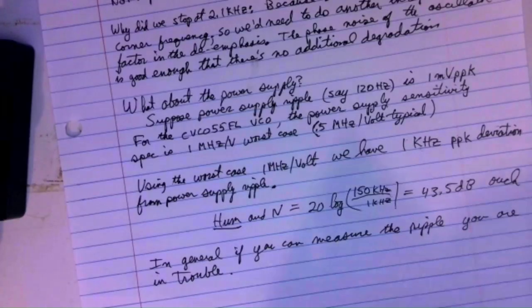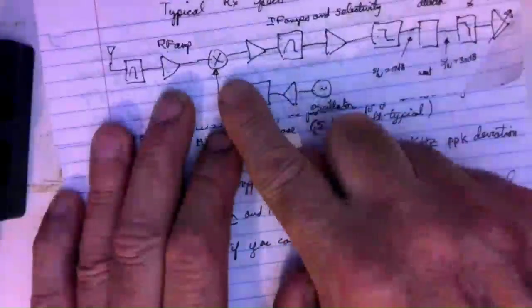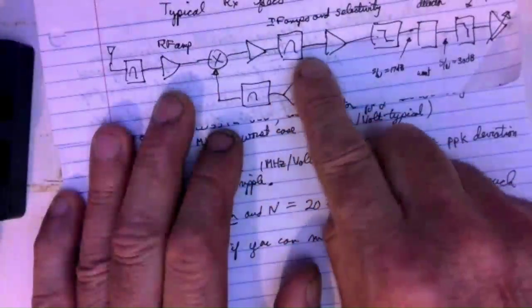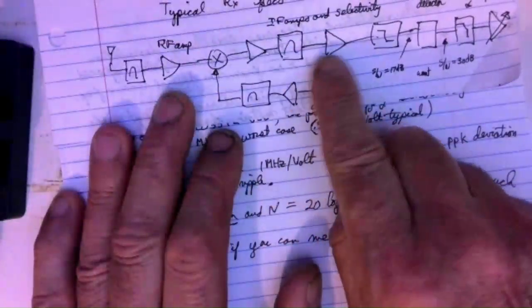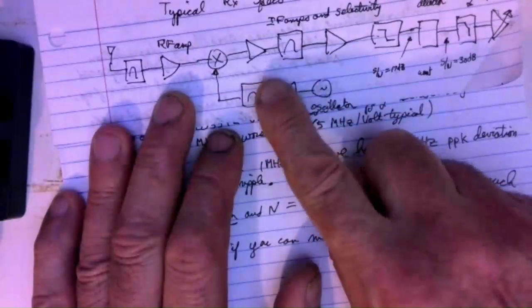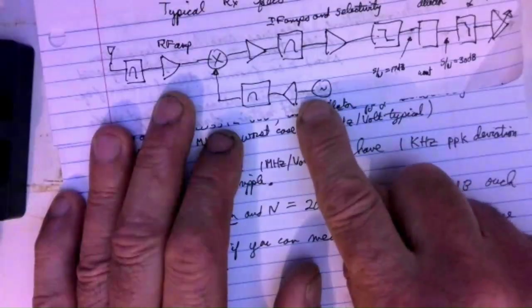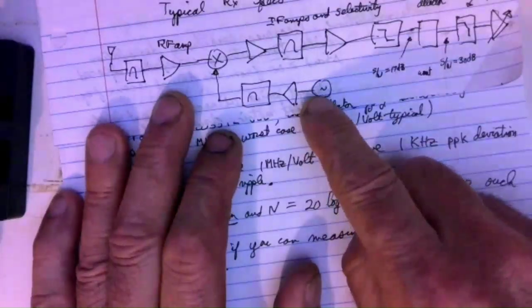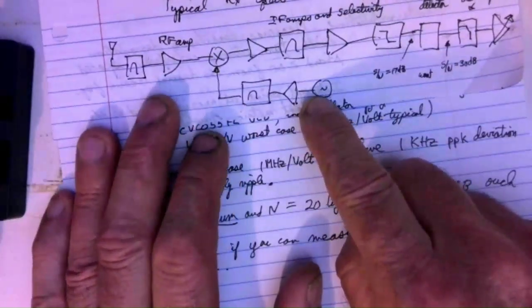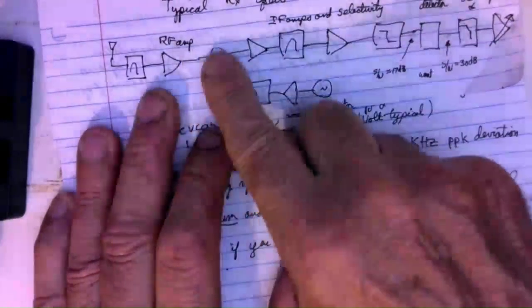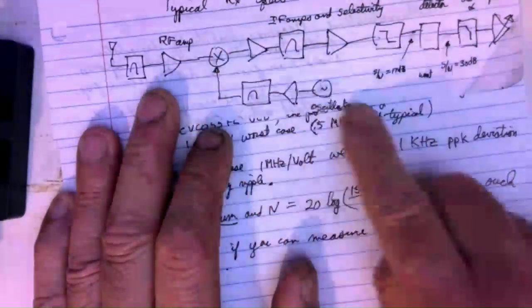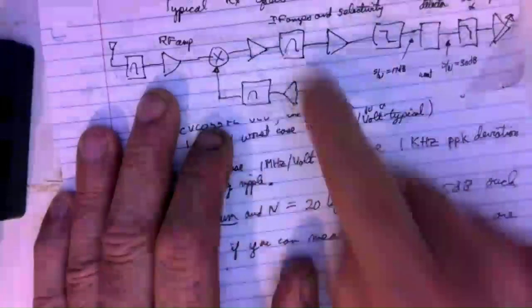The superheterodyne receiver is absolutely fantastic in what it offers you, in the ability to use one IF filter for everything. But holy smoke, you have to have a good oscillator, a really good oscillator. And we're not done talking about the oscillator yet. It causes other problems. And the mixer, a good oscillator and a good mixer to have a good superheterodyne receiver.